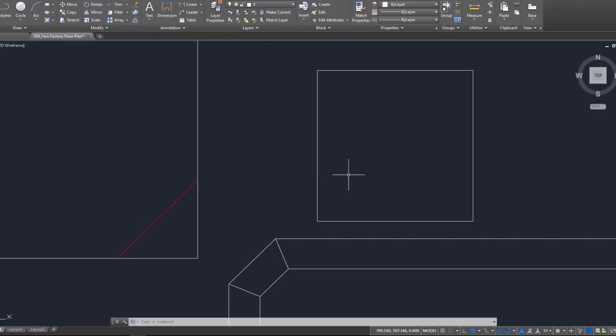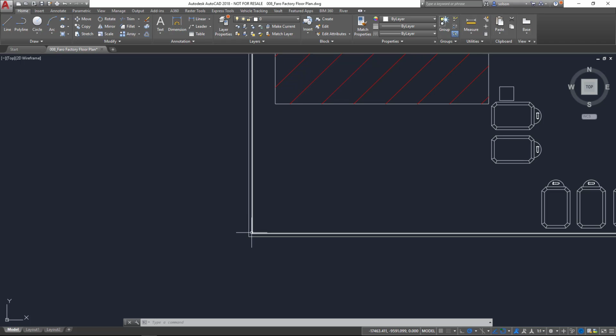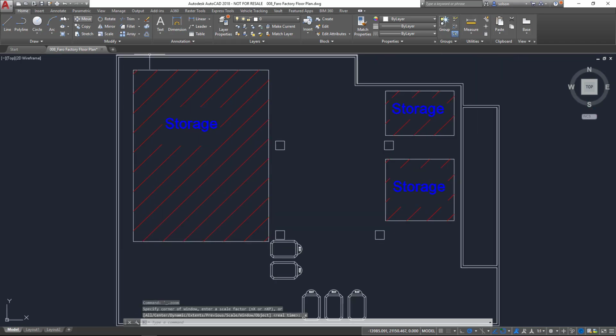That's just done by doing a regular old AutoCAD move. Initially, the origin was this corner here or this corner here, I can't remember which one. But I just did a regular old AutoCAD move, and I've saved this model. The next thing we'll do is go over to Revit, attach this model to that, and then start building from this.